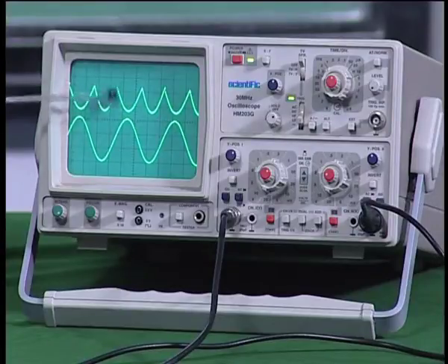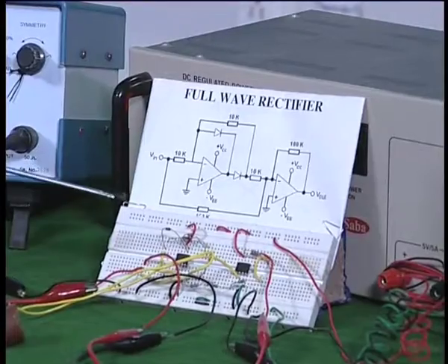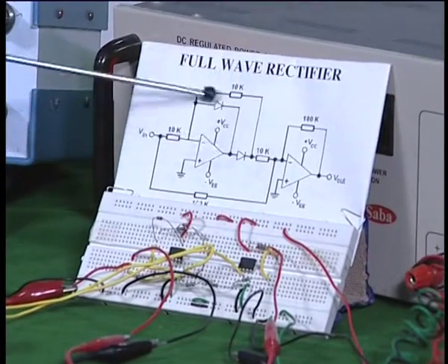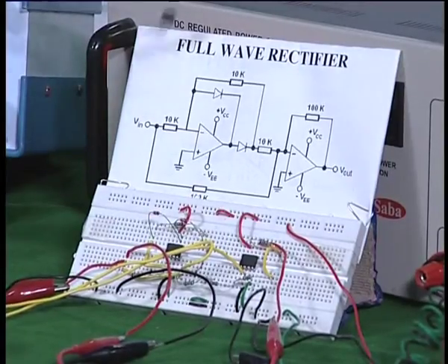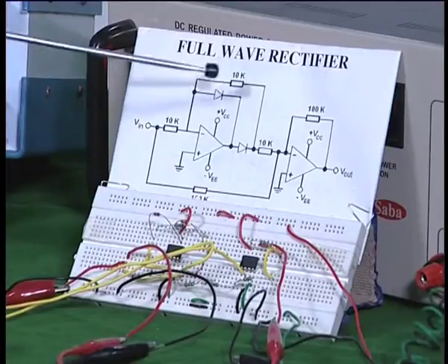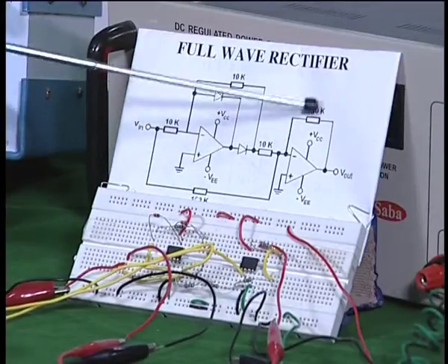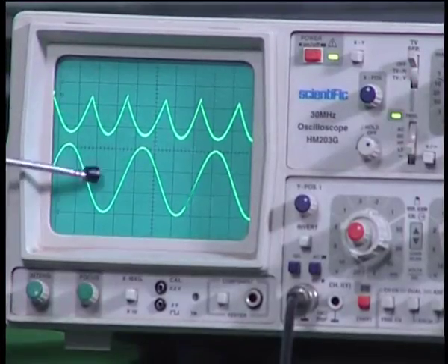You can see both the halves are coming in the bottom, and if you want the other way, if you want the signal coming up to the positive side, all that you have to do is interchange the diodes that you have seen in the circuit. For example, these two diodes, if you invert this diode and this diode, if you change the orientation, then you will get the full wave rectified signal corresponding to the other side. So, you can do full wave rectification easily by using one half wave rectifier and another summing amplifier. By properly choosing the gain, you will be in a position to get a full wave rectified output, as you have seen in the oscilloscope.